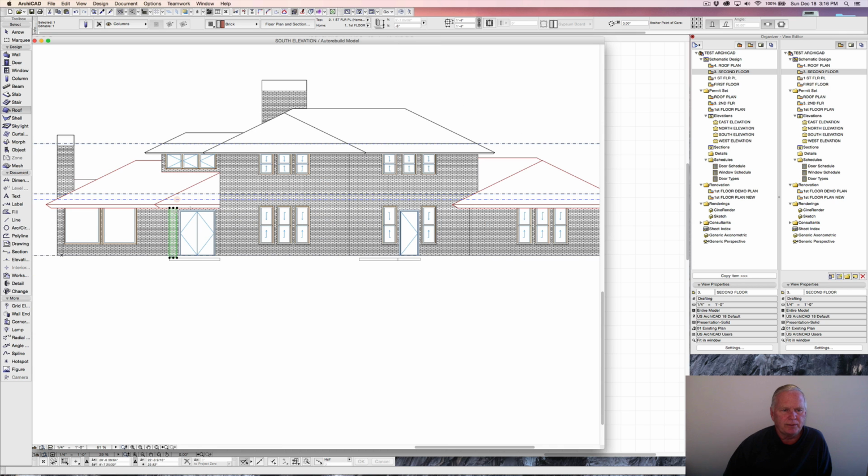All right, the next thing we're going to look at, we'll click off of that, is we set these first floor walls originally all based upon 0, and 0 being the top of the first floor. Now, as we look at this, of course, what you will probably do in the future, because it is what I do, and of course what I do is correct, is set top of foundation as 0. And thus you would actually see more wall here.